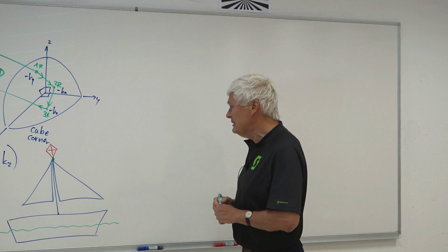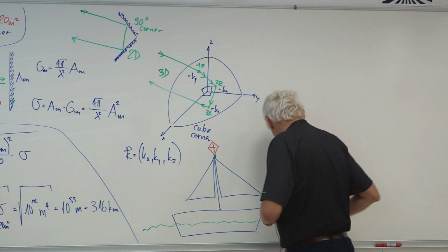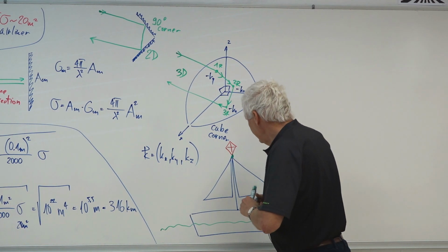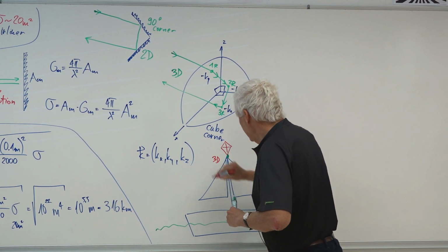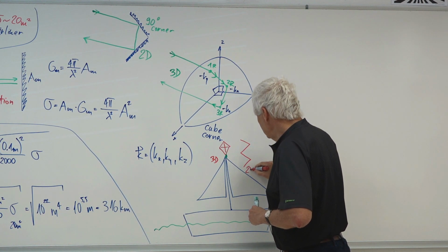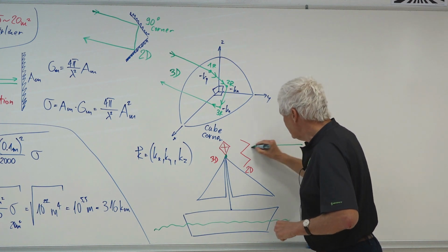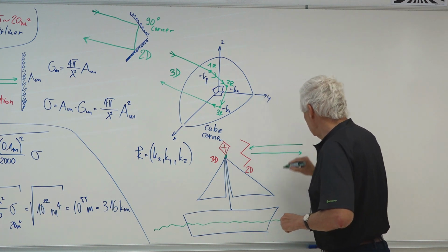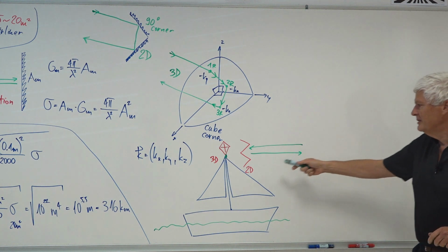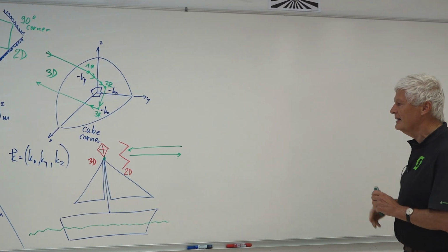Even on sailing boats, you may have 3D reflectors. This is a 3D reflector. You may also have angled strips at right angles, just 2D reflectors, because all the radar you can expect here always comes from the horizontal plane. It's not necessary to correct for the vertical component kz. It's enough to correct ky and kx to have the reflection.